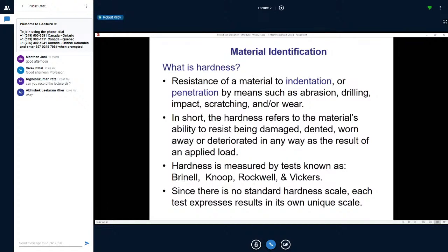When we're doing hardness testing, the best way to approach it is to choose whichever piece of equipment you've got and stay with that piece of equipment. So don't take, I don't know, a Vickers tester and try to convert Vickers readings back to Rockwell. Whatever machine you've got is the one you use, and probably Rockwell, because it's just the one that's most common.